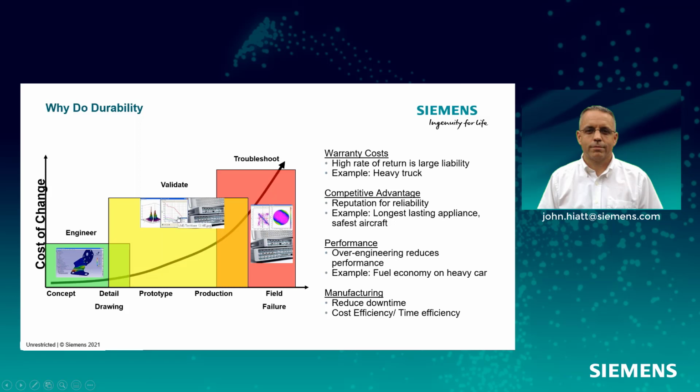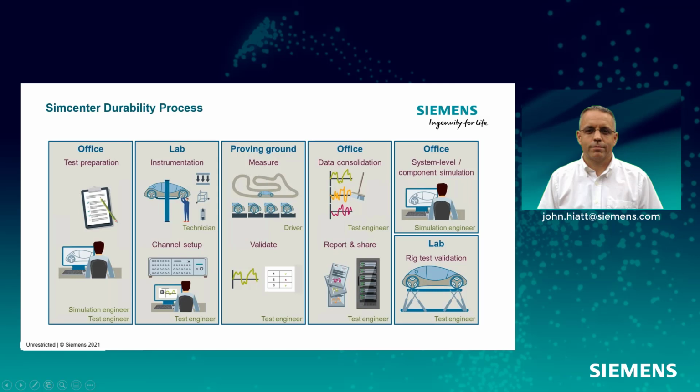I'm a test person and I live in this validation world. So I have two missions as a durability test engineer: I validate designs, and then I validate models. I take measurements that validate the models, and they do the fatigue in the models because they can quickly make design changes and assess the fatigue life. As a test person, I'm validating the designs, correlating the models, and hopefully minimizing the amount of development work I do in test, because test development takes a lot of time and money.